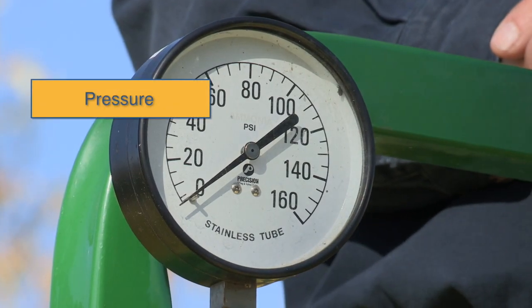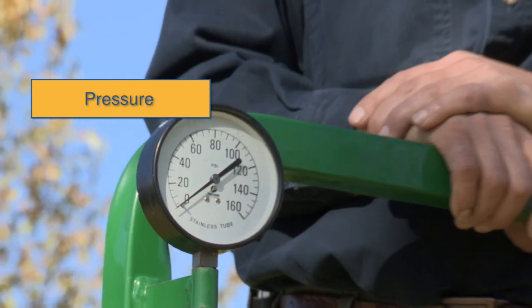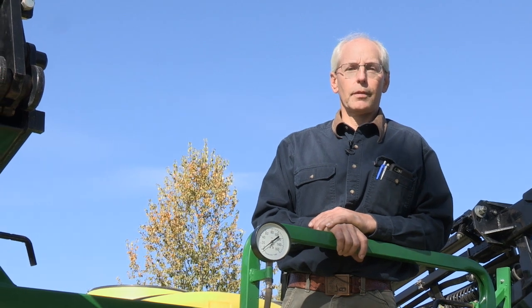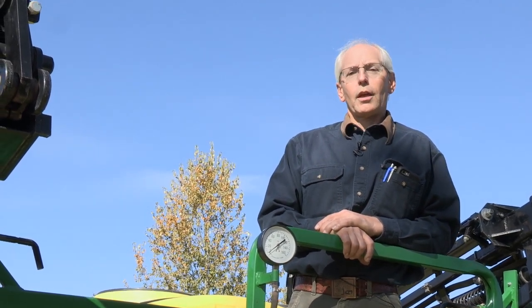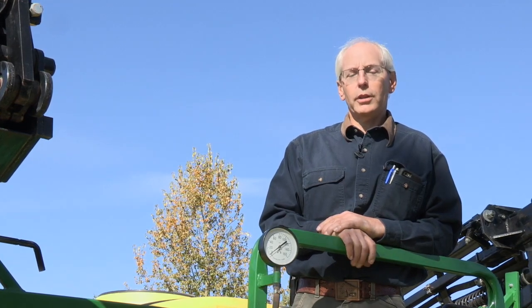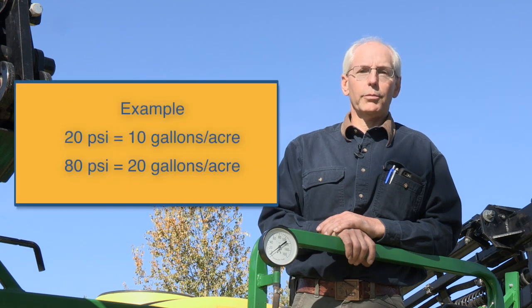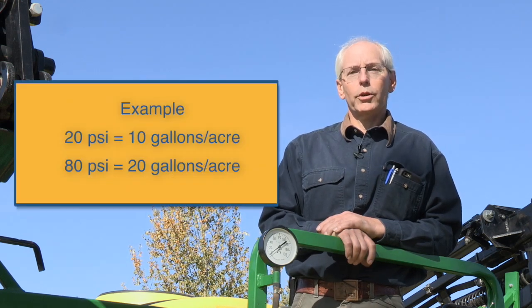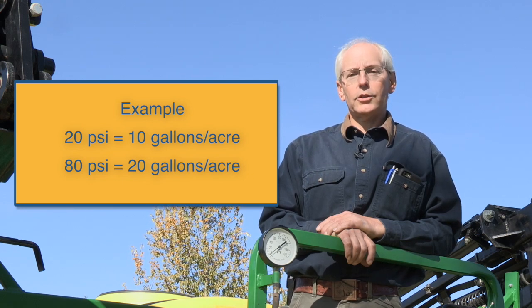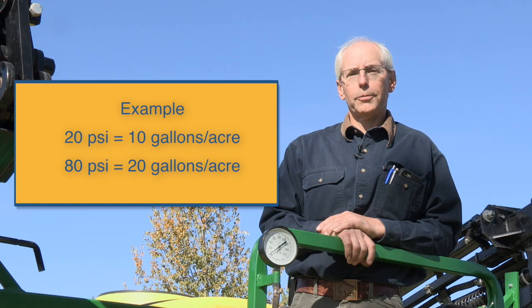So unlike speed, which has an inverse relationship to application rate, pressure has a direct relationship. As your pressure increases, your application rate increases. But remember, it takes a fourfold change in pressure to bring about a doubling of your application rate. For example, if you start at 20 pounds per square inch and have a 10 gallon per acre application rate, you'd need to go up to 80 pounds per square inch to get a 20 gallons per acre application rate.